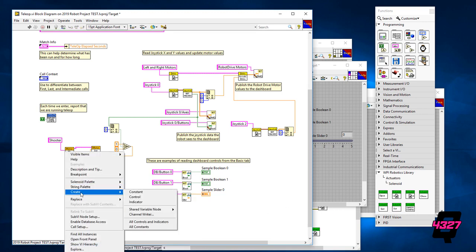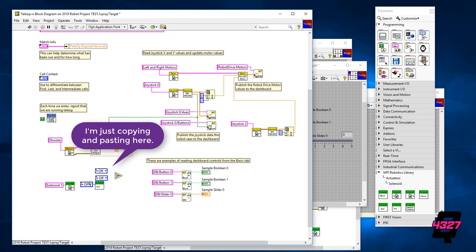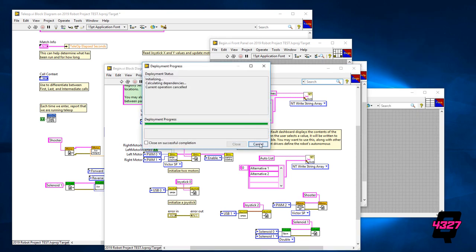For single solenoids, you only need one slot, while doubles need 2. Logistically, it is best practice to go in sequential order and make them neighbors. So if you're using a double solenoid, use slots like 0 and 1 instead of 0 and 5. You'll thank yourself later. Let's get to that teleop. Use a button to control them with either forward, reverse, on, or off being your values instead of numbers.